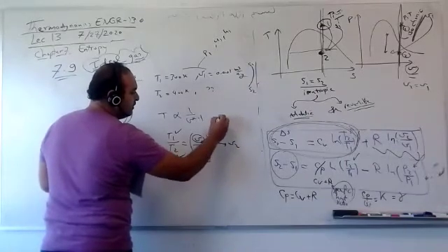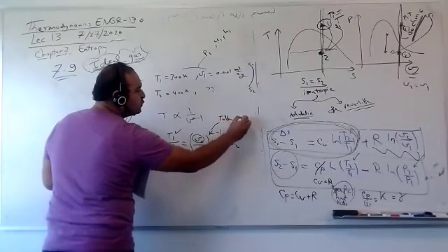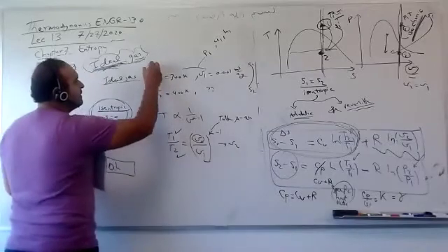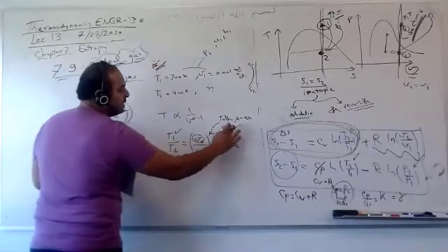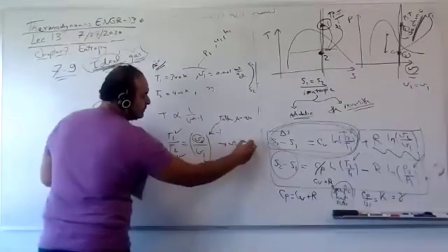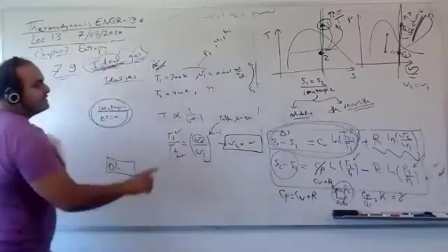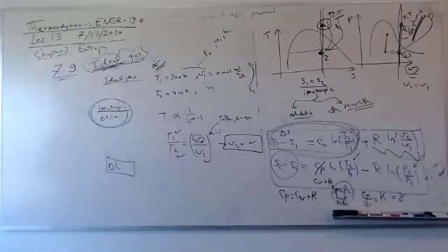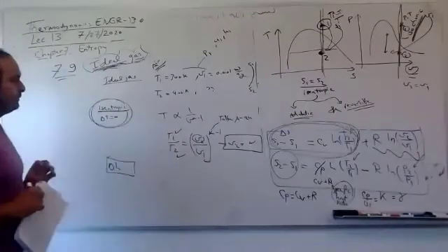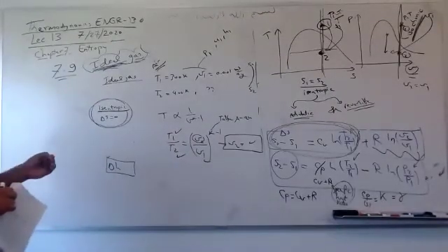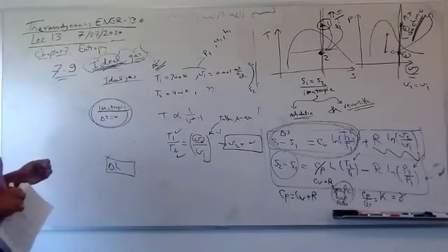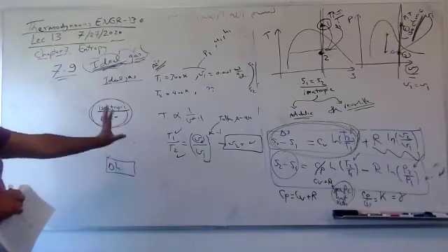K is from table A-2. Let's say this is air. You can easily get the K. So you can get V2. Just a simple equation, the same as this one. This is only for ideal gases. Do not use it for anything else. So this would be part of the problem. In a quiz, I can ask you for this only.